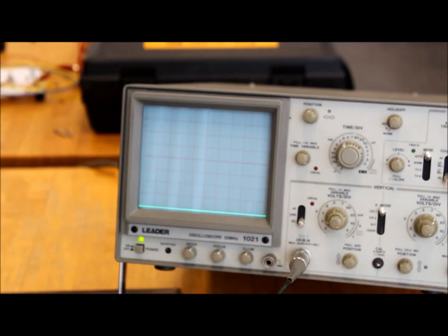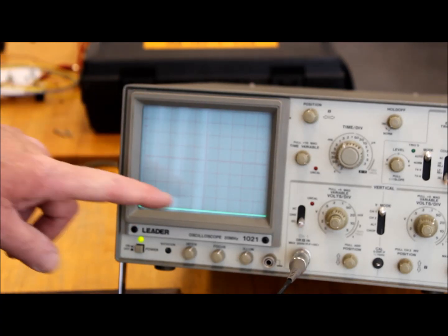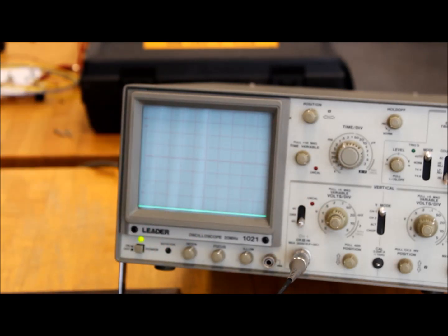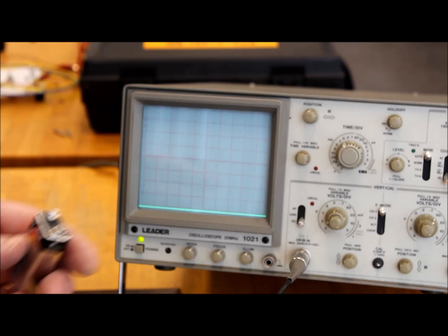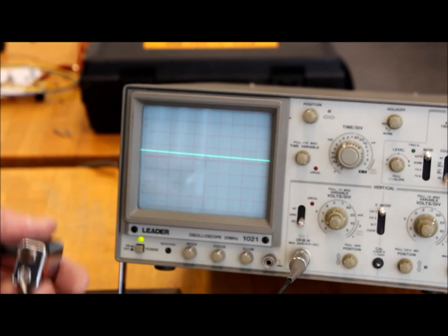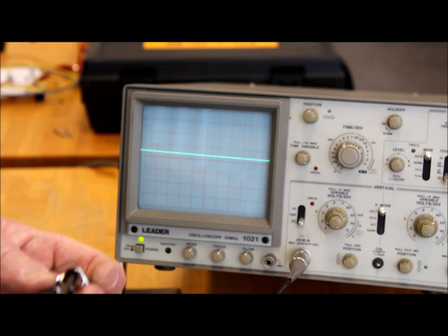So remember the oscilloscope from another lab, and I just have it set up here again just to remind you. Volts is up this way. Right now it's set for 2 volts per division, so 2, 4, 6, 8, 10. I have a 9-volt battery here. If I just hook my scope up to that, it reads about 8.5 volts, just to the 2 terminals on my battery.